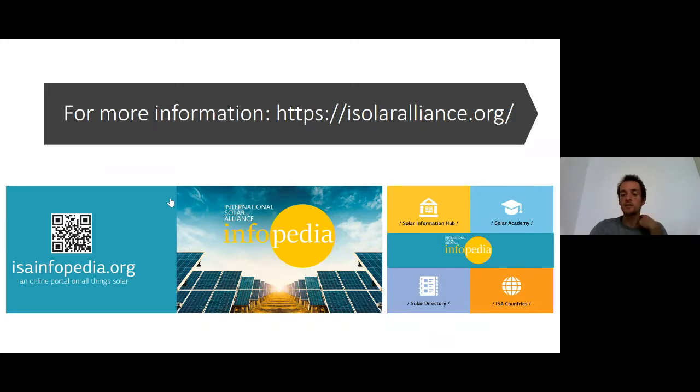Another answer is that you can have multi-junction solar cells for some specific applications, where you basically stack different materials on top of one another. With these different materials, you are able to absorb a bigger part of the solar spectrum. Currently, the maximum efficiency of these technologies is around 50%.